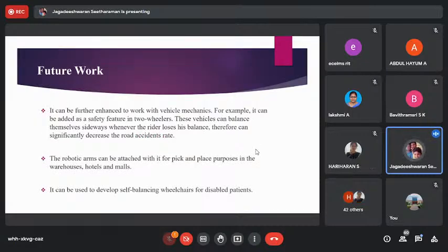The project aimed to fabricate and test the working of the self-balancing robot. The design and fabrication of the robot are correct with the fixed position. Its components are designed for the maximum amplitude of vibration. The robot body can tolerate sudden force to a good extent, in the case of failing horizontally on the ground, when it goes out of the limited balancing zone. The maximum zone is minus 25 degrees to 38 degrees of tilt angle, in which the robot can balance itself without any external help, and this is analyzed properly.